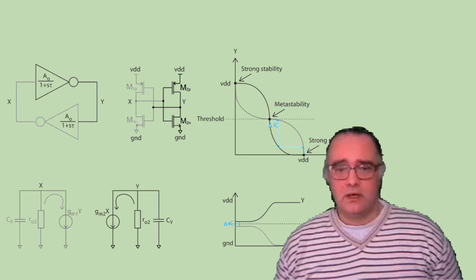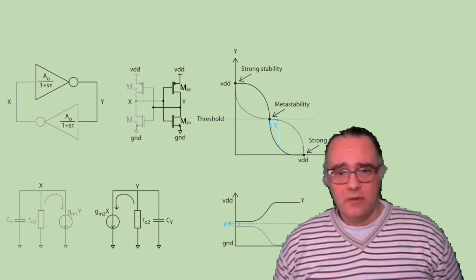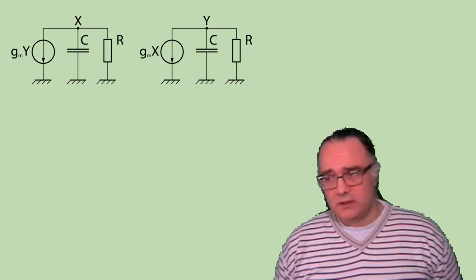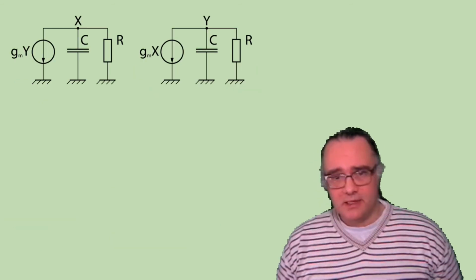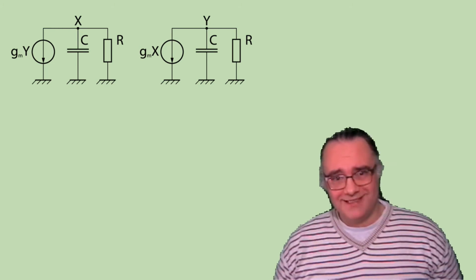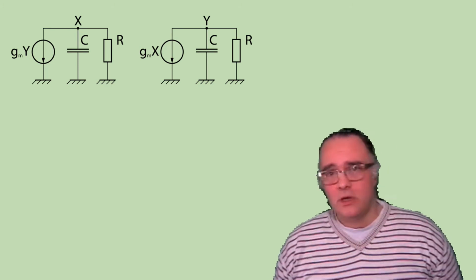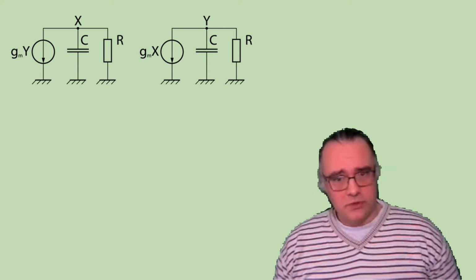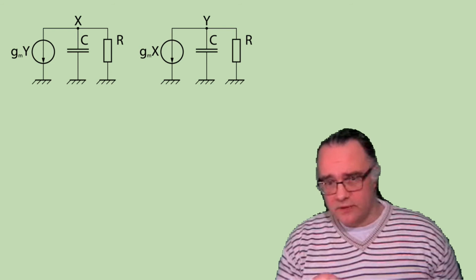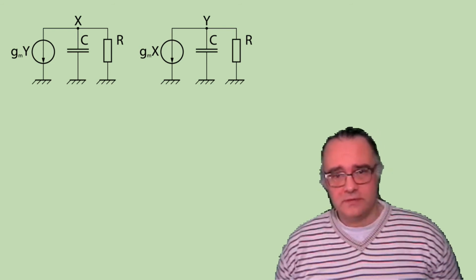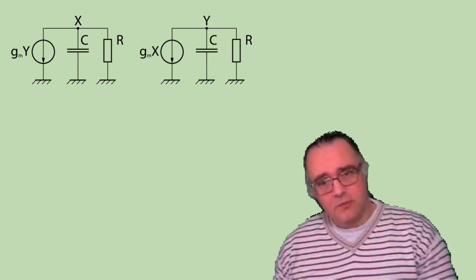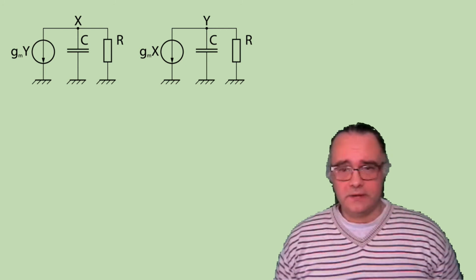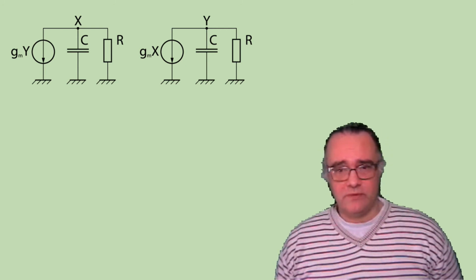to ground. Now, of course, the comparator's inverters are balanced, so we can draw two equivalent circuits for the single pole model that consist of a voltage dependent current source, equivalent capacitance, and equivalent resistors in parallel, and then another group of voltage dependent current source, equivalent capacitance, equivalent resistance.